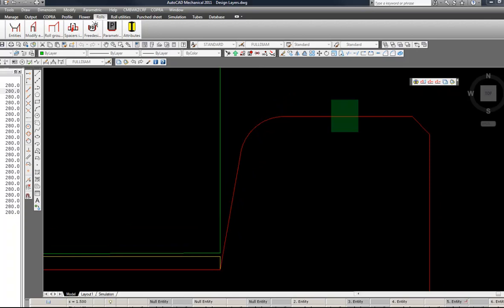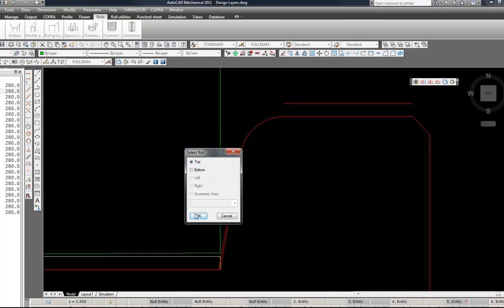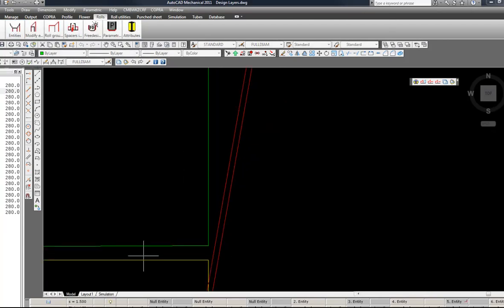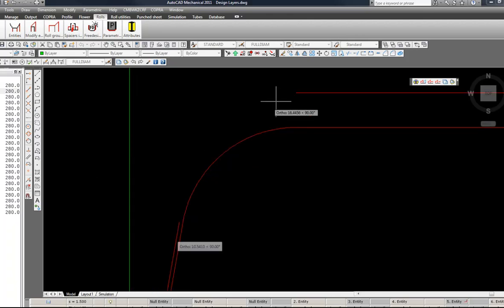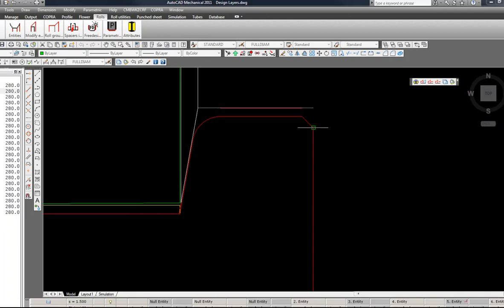Again, I'm going to explode the bottom roll, offset for 1.5, material setting gap, and then some running clearance here on this angle. Entities with crosshairs for the top roll, and it will be the apparent intersection of this roll here and this entity here. The apparent intersection again now of this diagonal line here to the horizontal here, and then I can use object tracking in AutoCAD to give me this position, select and then right click to enter the command.